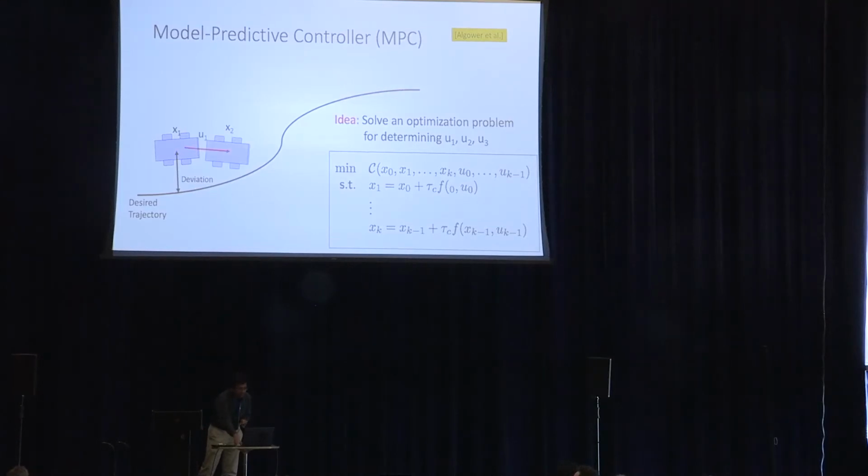In model predictive control, we consider a finite time horizon. So it's basically finite horizon planning done on differential equations or continuous state spaces. Let me apply U1, and suppose I get to x1, then I apply U2, I get to x2, then apply U3, I get to x3 and x4. So I imagine a finite time horizon into the future. And so this U1, U2, U3 are my unknown control inputs. I don't know what they are. Correspondingly, x1, x2, x3 would be my unknown future states.